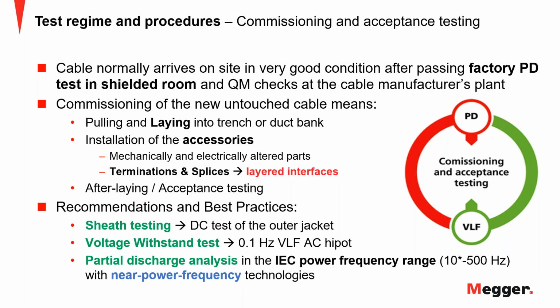And so your commissioning test should be carried out in a way to focus on this area. So you are focusing on the general integrity of the insulation, the integrity of the outer sheath, and the integrity of your joints, or of your splices.